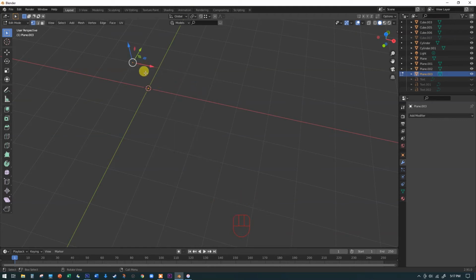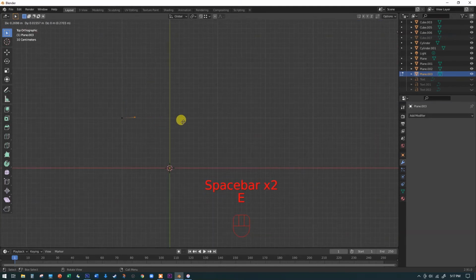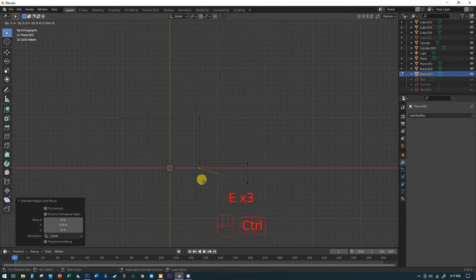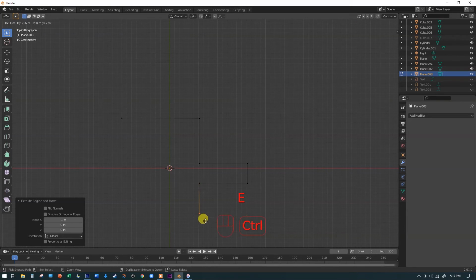You can do this in any view you want, but I think it works a little bit better if you're in top view. So I'm going to hit the E key to extrude this, and then I'm just going to come off at an angle here. This is actually a really good one for turning on your increment snapping. If you just turn that on and leave it on, then you don't have to worry about making sure that the lines are straight. Then I'm going to extrude this way and hold down the snapping, and I'll extrude again, and I'm just going to keep on doing this until I've got the floor plan that I'm looking for. Or, like I say, if you're tracing over an existing plan that is there as an image, this is a great way to do that.